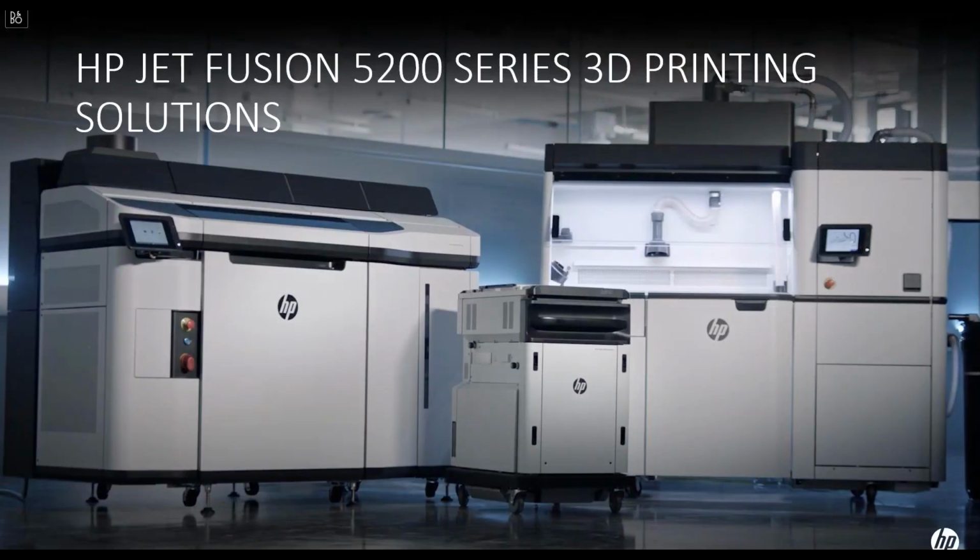You can go to the next slide, Max. So this system is designed for high volume, and it consists of 3 different pieces. On the left, you've got the printer. In the middle, there's a build unit. Most systems typically start with 2, but you can have upwards of 4 per system. And then there's the processing station on the right. All of the powder is handled at the processing station. There is an 80% recycled, 20% new mix of powder for each build. This allows them to drive down the cost of the parts.